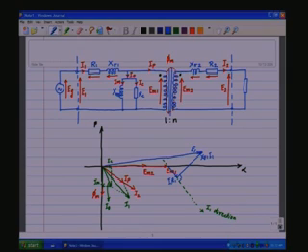Now, we need to know what is the E2 phasor. We know that the secondary side Em2 is along this, this is the Em2. Now, Em2, look at the directions at an instant, because the current is flowing in this direction. Em2 minus the drop across the secondary leakage reactance minus the drop across secondary winding resistance I R2 is going to be E2.